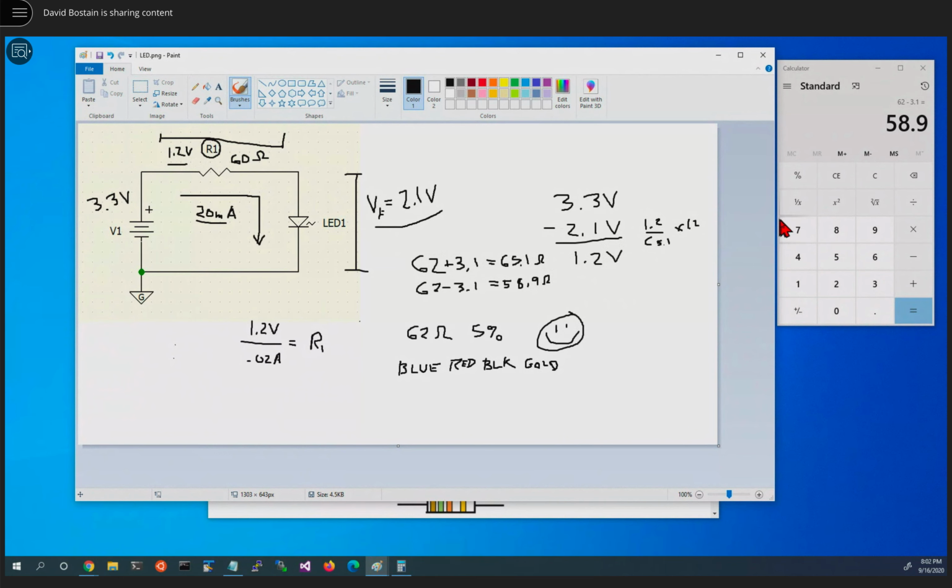So we'll get two numbers as we go along. So what do we need? Actually, we should do it the other way. We should take the voltage, which is 1.2 volts. We should divide that by 65.1. That means our current here is going to be 18 milliamps. Is 18 bigger than 15? Yes. So we know we're safe if it's that value. Now that value times the 1.2 gives us the power dissipation, which is 22 milliwatts.